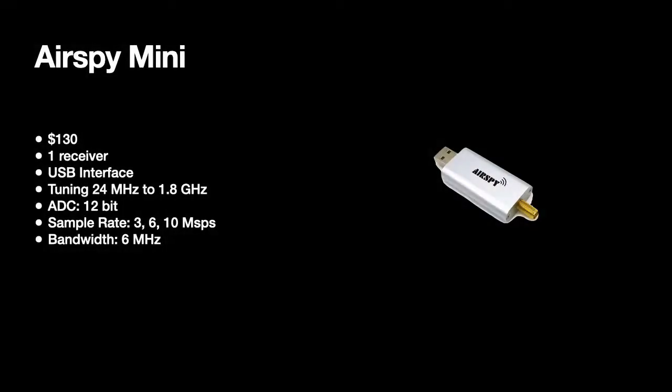Slightly more expensive and of course better quality, we get the SDRplay. It's about $130. Again, like the RTL dongle, it's one receiver and a USB interface, and it tunes similarly to the RTL dongle. However, it has a 12-bit analog to digital converter, and it has a maximum bandwidth of 6 MHz.